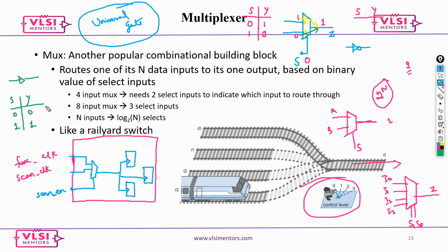So if you look at this particular thing, it is going to be kind of a mux. Say this is your select. Now say this is 0. When you give 0, 0 is going to come out. When you give 1, 1 is going to come out. So this is going to be your Z. So this operates like kind of a mux, not mux, I mean a buffer.